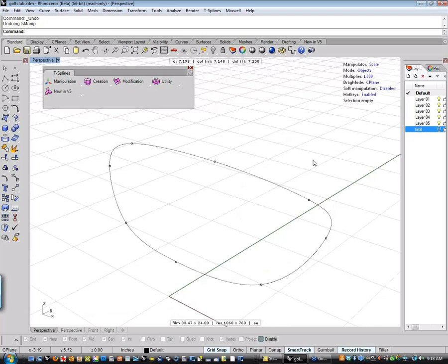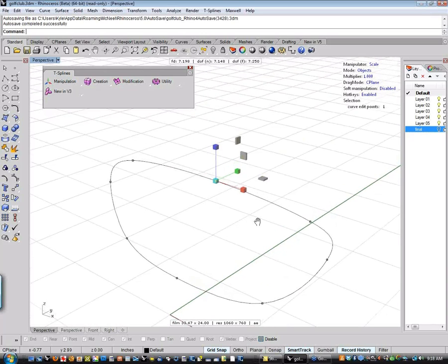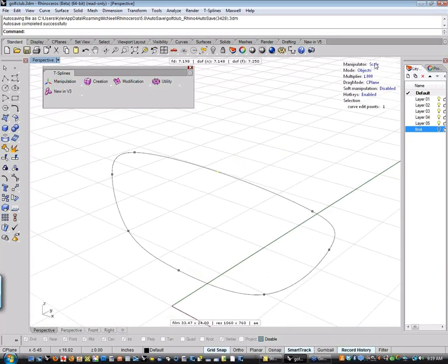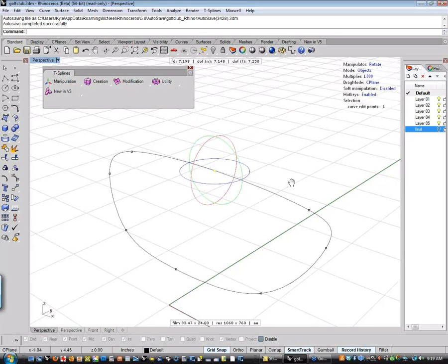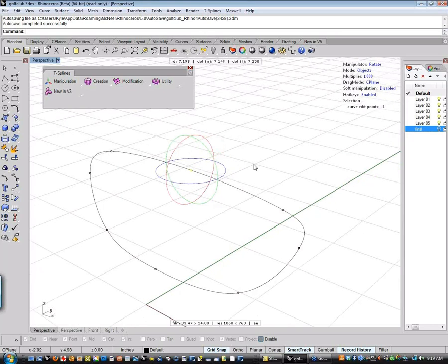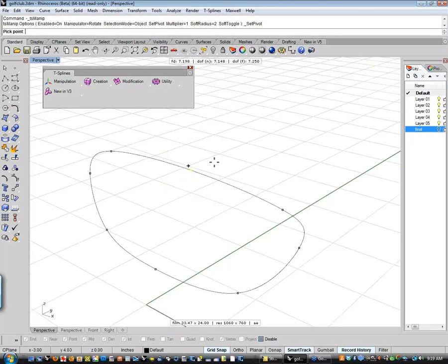To move the manipulator, we talked about that briefly when I was talking about the other thing, but it is particularly useful in the rotate manipulator. If I hit the T key, which is the hotkey for relocating the manipulator, the manipulator and the triad are going to disappear. Get my grid snap on.